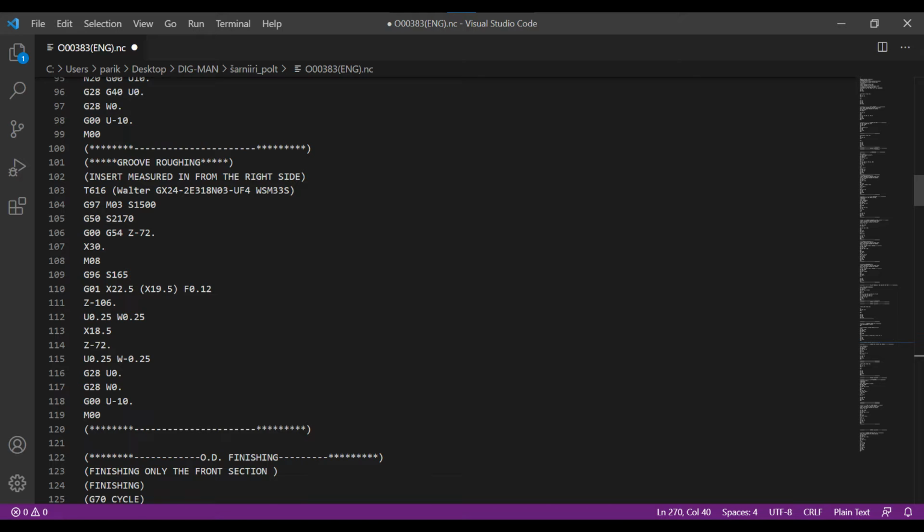We start up the spindle, rapid feed to nearby position, start the coolant, switch to constant cutting speed, feed into the material and start machining along the x-axis. Once the machining is complete, we move away from the workpiece and return to home point.